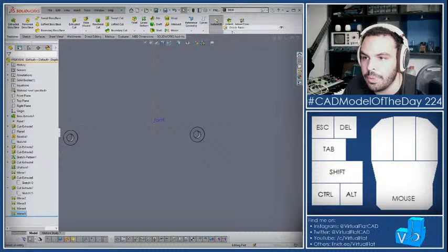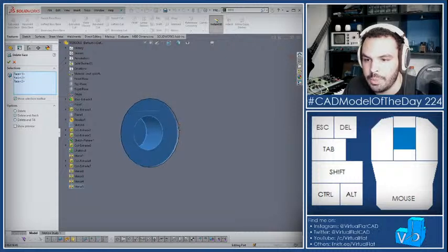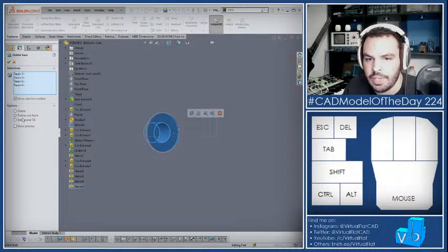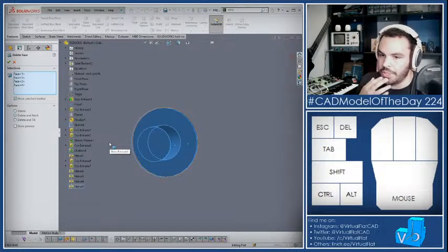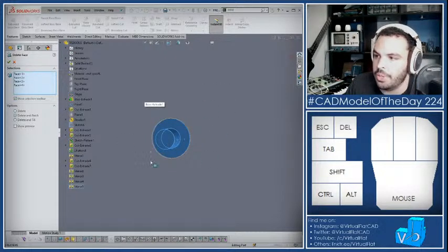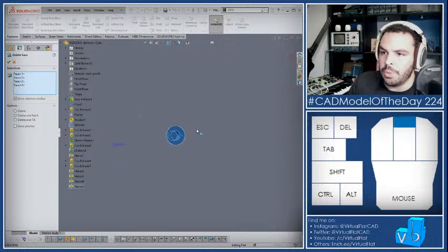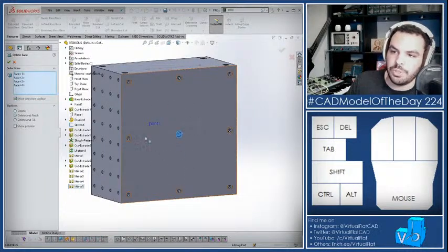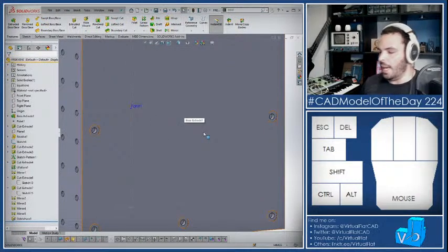All right, so to get rid of this thing, I got my delete face tool up, and I'm just gonna delete all the faces of that hole. If I say delete and patch, it means that it destroys all those faces and it patches it over. And you might say, well, with what does it patch it over? Well, it's this surrounding surface, and that's what makes SolidWorks different than, for example, Blender. So SolidWorks actually keeps track of the underlying equations of all the surfaces. So it's able to extend it for a patch that doesn't actually exist. So when I hit OK, that hole disappears and I never have to worry about it again.